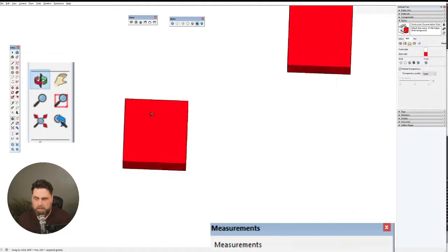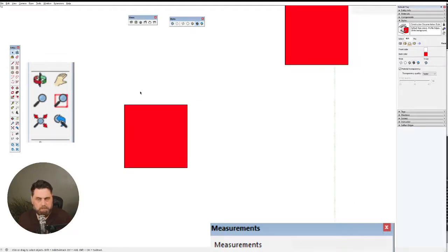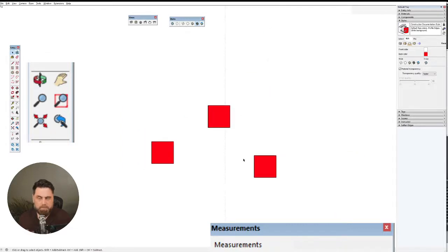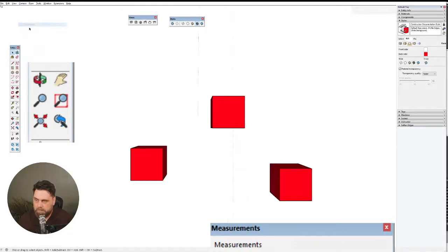Okay. And if you accidentally rotate, then we can just hit Z to get us right back where we were. Okay. So this is for 2D drawing in SketchUp. I'm not going to get into that right now, but if you ever do that or take my course where we talk about 2D drawing, that's how you navigate around there. So we could now go back to camera perspective.